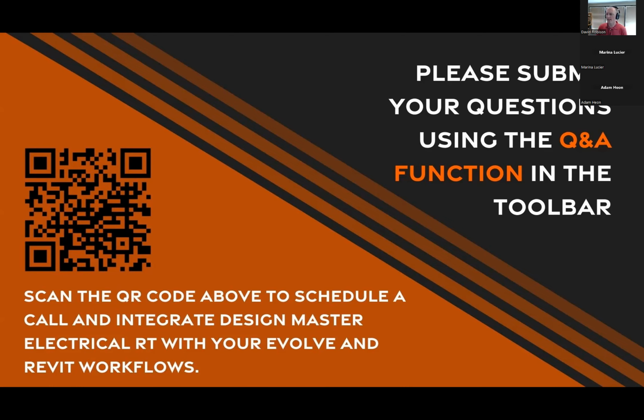Can we relink the one-line detail family if the panel got deleted in the model? You can. If something doesn't exist anymore, the software will highlight it and say, hey, do you want to link this? And you can run our change link command to point it to a different panel. So we have the links that are created automatically when you insert stuff, and then you can update them if you need to.